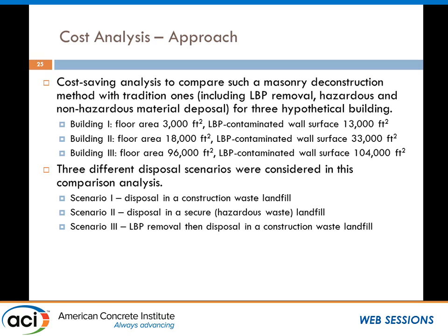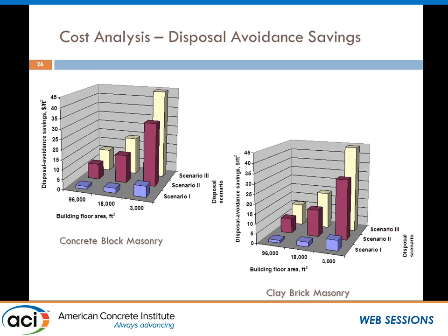So scenario 1 is to dispose of it in a construction waste landfill. That's a regular landfill. Scenario 2 is to dispose of it in a secure hazardous material landfill. Again, that's very costly. Scenario number 3 is to remove lead-based paint, then dispose of it in a construction waste landfill. So we compare our practice, which is to directly demolish the whole structure and reuse it back in concrete, to see how much money we can save. So these are the results.